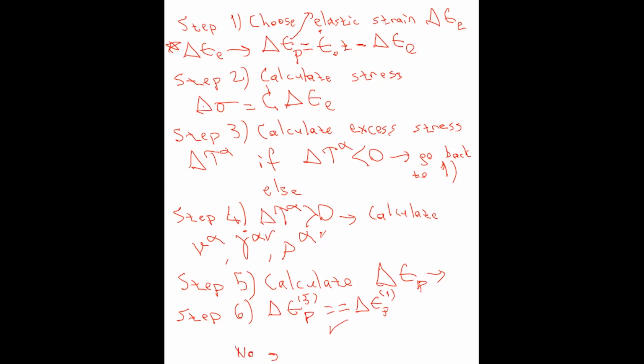If not, what should we do? We need to choose a different elastic strain and follow the same procedure. Go back to step number 2 till you converge, till your stress strain curve converges.